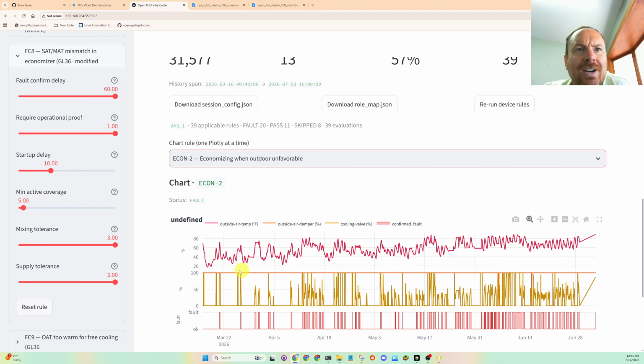That this outside air damper is either 100% closed all the time or 100% open. I think it's just closed. And then I have a hunch that this building's economizer dampers may not economize at all, and that's why they need the chiller so much.